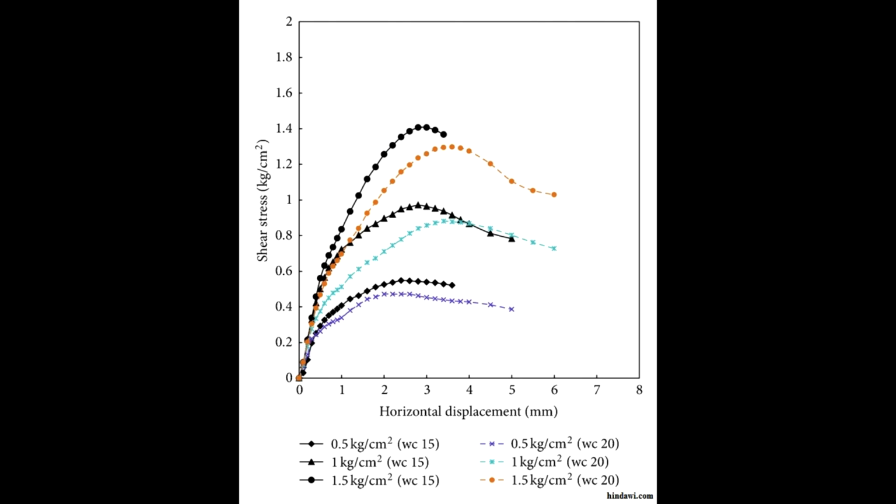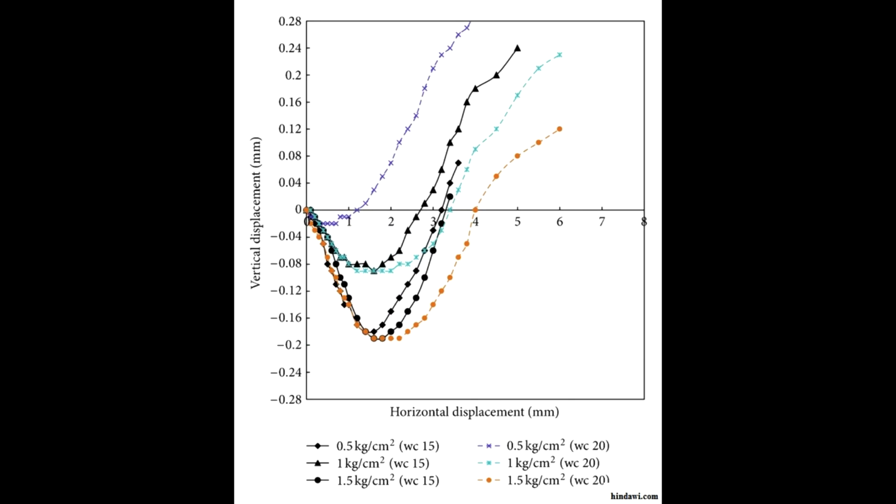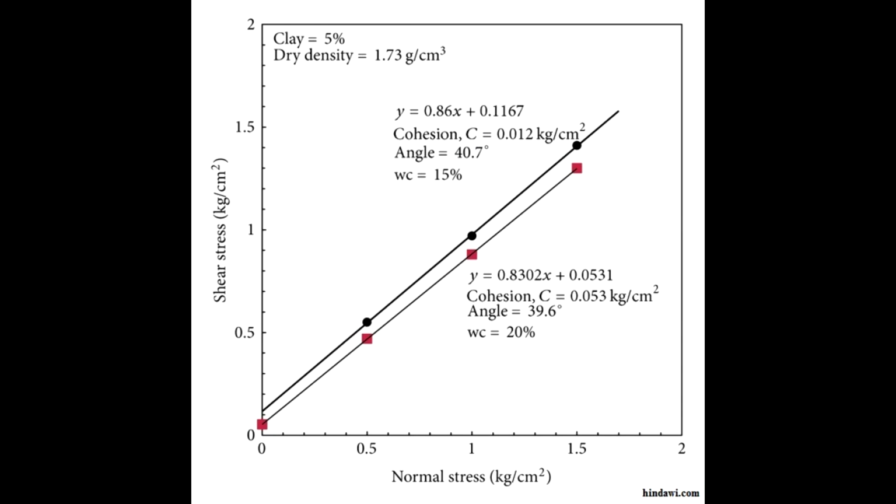When all necessary calculations have been completed, one must plot the shear stress versus the horizontal displacement in Excel. Next, plot the horizontal displacement versus the vertical displacement. Include all specimen data on the same plot and label the normal stress for each curve. Finally, plot the Mohr-Coulomb failure envelope. This is the normal stress on the x-axis, shear stress on the y-axis. Both axes must be on the same scale. Determine the friction angle for the material and label it on the plot.